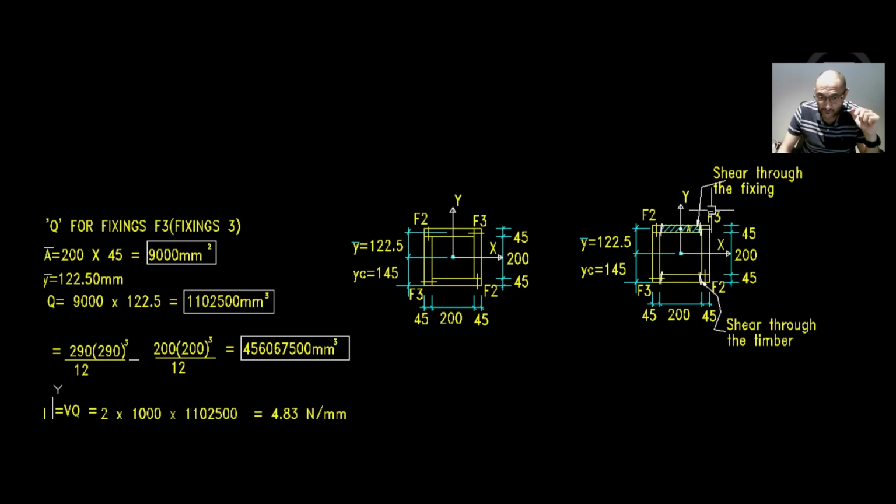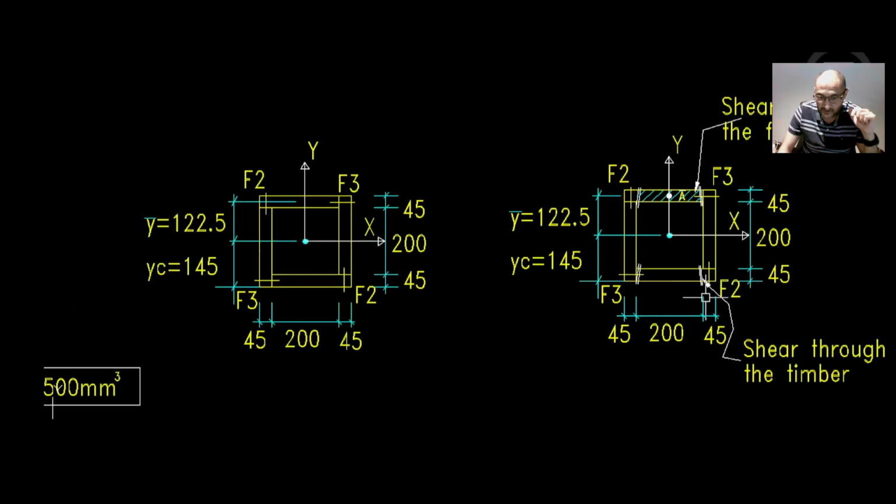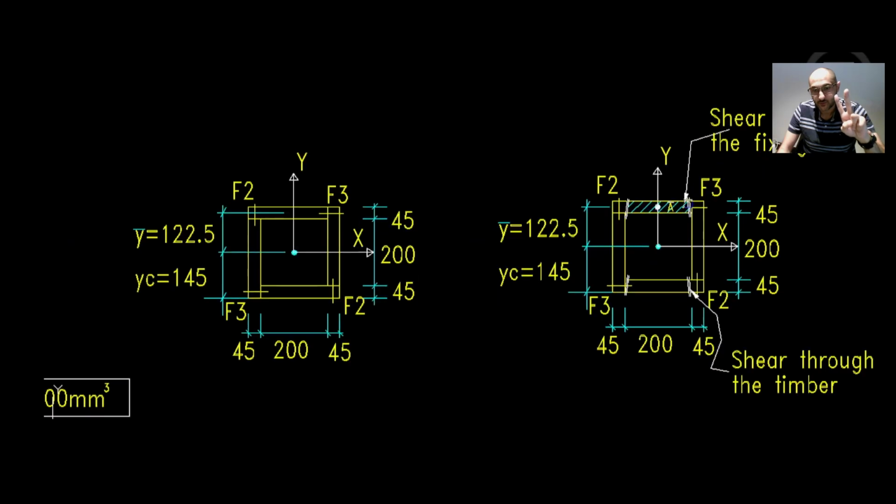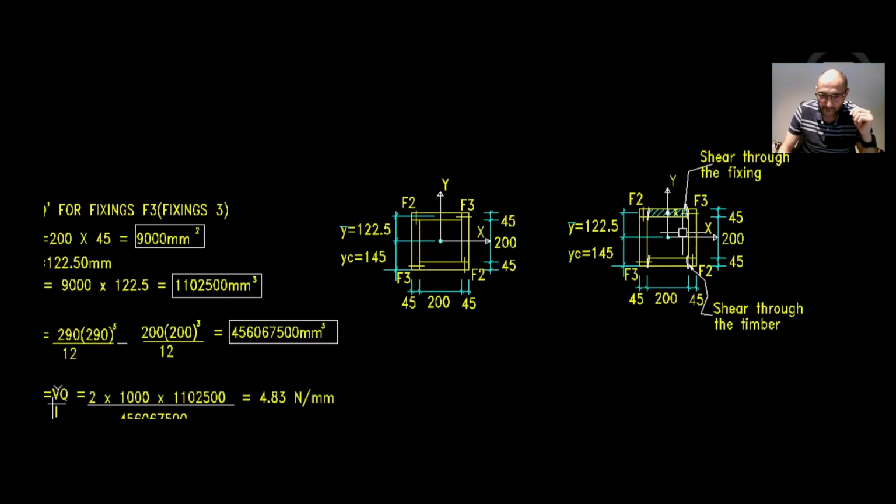So we shear the right-hand side, right down, and it's going to go through the timber. And then on the left, we also shear vertically. So there's 2 shears. Then we take the first moment of area between the 2 shears. You get the idea? And the shear cut, if you noticed, is symmetrical. Okay, this is the trickiest part of the whole problem.